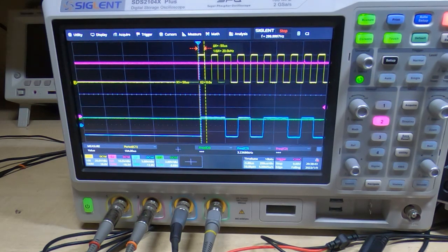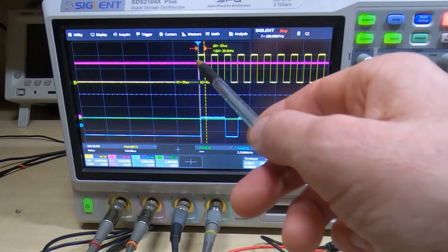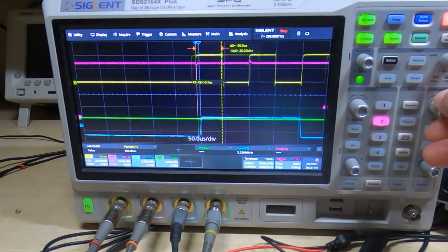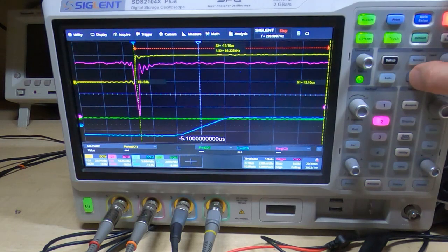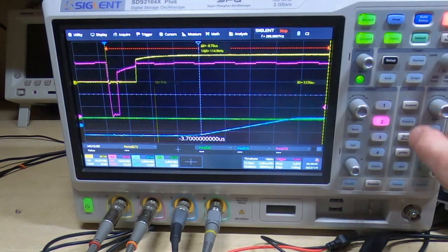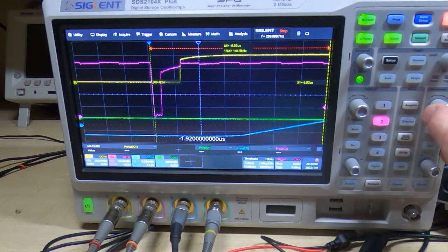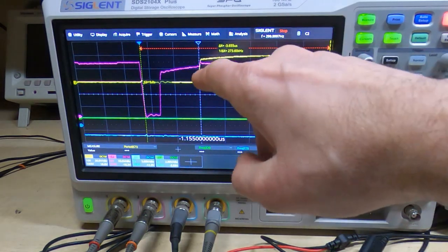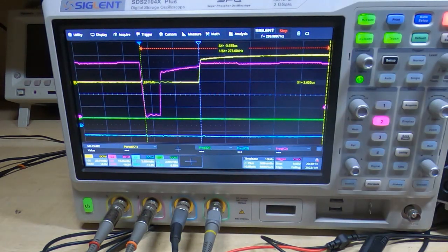So now we know what's causing it, how do we go about correcting it? Well, it's actually very straightforward. As I say, the circuit was designed from the systems level approach, so I already knew what resources I had on the Z80 board, the processor, and all we need to do to get rid of this is to guarantee, zoom back in, we just need to guarantee that all the clock edges occur within the time period of the start pulse.